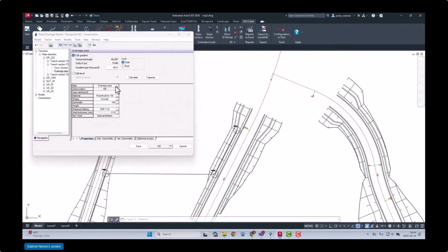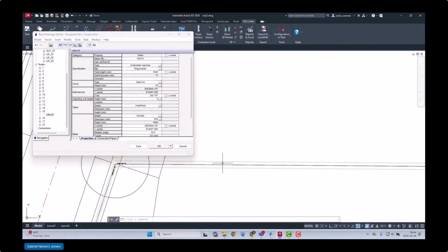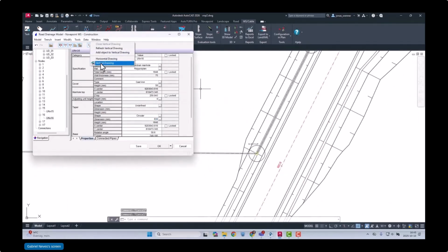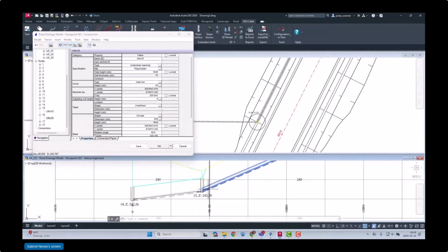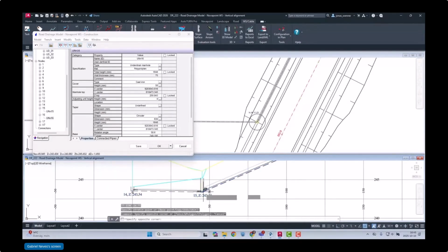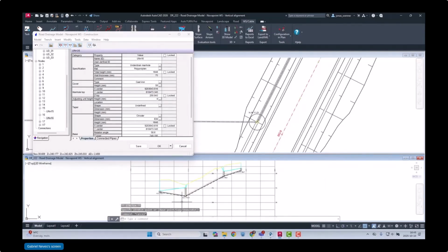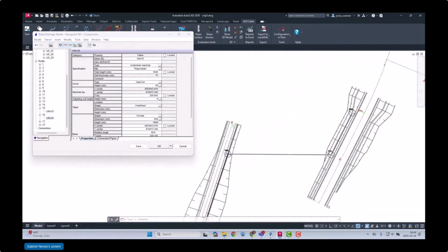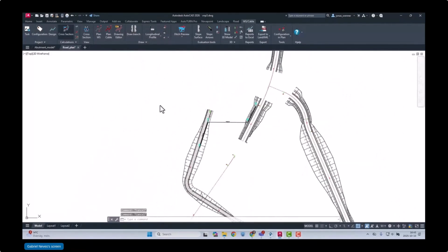And you can model almost everything that is connected to pipes with this tool. You can connect electrical cabling, conduits, drainage, water pipes, and also combine trenches with a lot of pipes in the same, and the software will always create a 3D model of it with calculated volumes, calculated numbers and length of all the pipes included, and so on. And you will also have all the stakeout data needed for the construction of this trench. So all is integrated here.